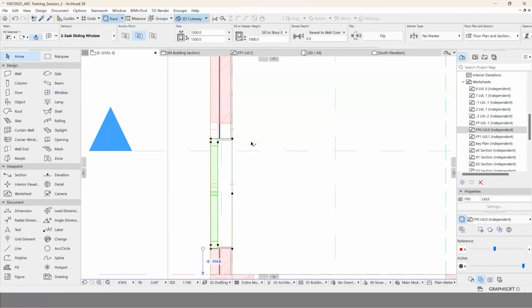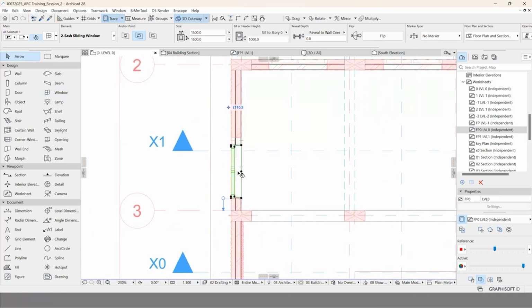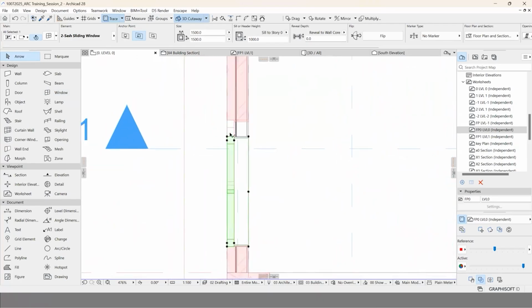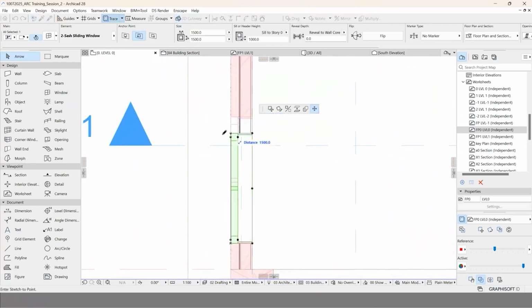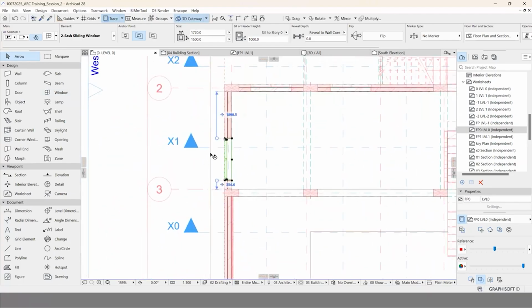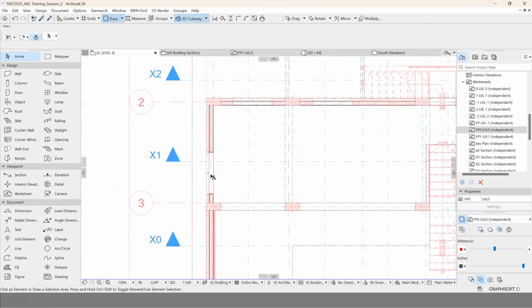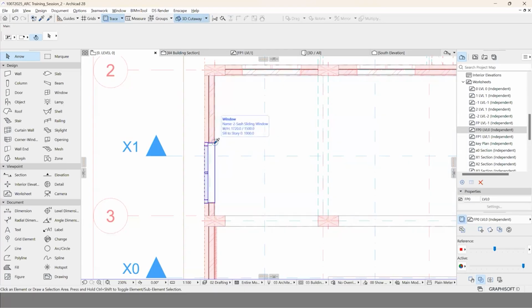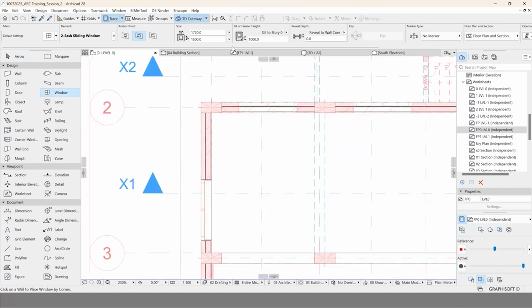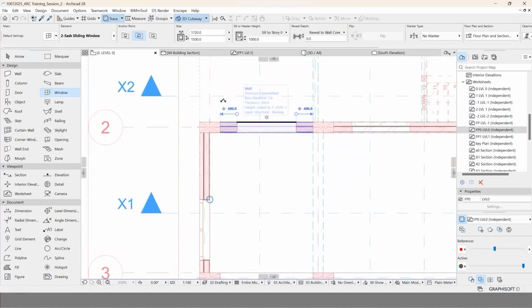So when I click right now, as I mentioned, this is a small window because I did not define the dimension. But we have an option when it comes to doors and windows of Archicad, that is being able to edit it. So if I want to stretch it, I could just click on one of these points, and in the pet palette, I have this option called Move Node. If I take that, I can stretch the window, and it will affect only that particular window. Now, if I want a same window to be placed here, I could just hold Alt and move my cursor. And when the window is highlighted, click. What it does is all the properties of that particular window will be the new settings. Now using that, I can just place the window.